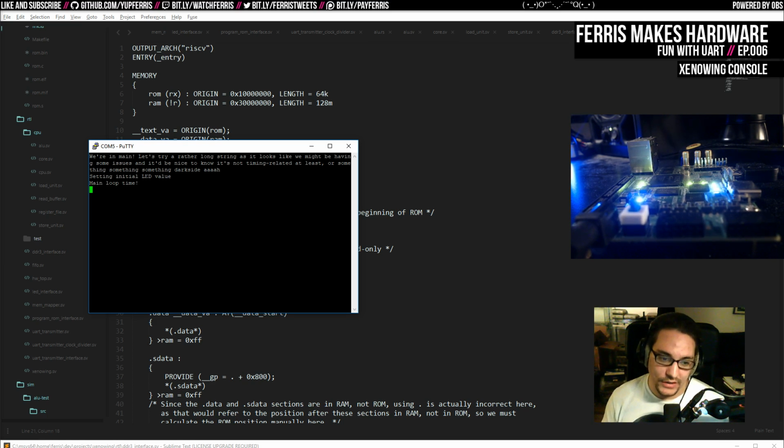We're gonna have to do some register setting over I2C, and the last time I did that, it was pretty finicky. So I would really like to expose that to the software as much as possible, so that we do as much of that there, and then we can also print out register status from the HDMI transmitter, and be able to debug things progressively that way. So, I mean, we will still be changing the hardware and iterating on that, but it should be a lot easier for us to see what's going on as we debug that, just because we have this simple output interface. So that's the first reason.